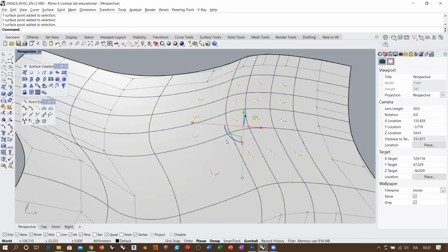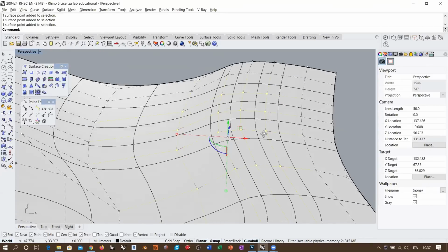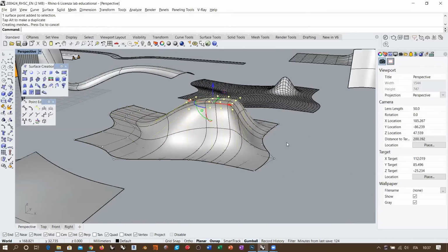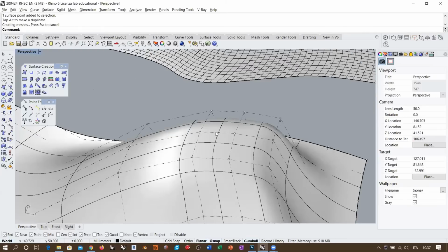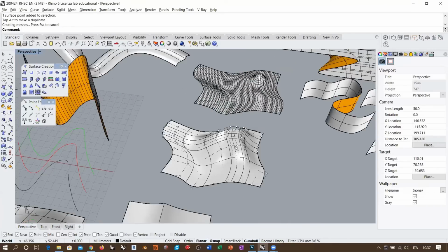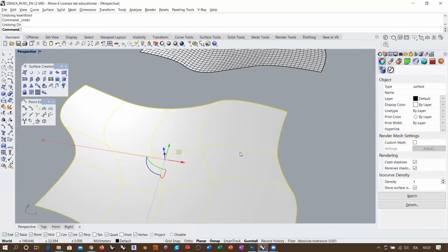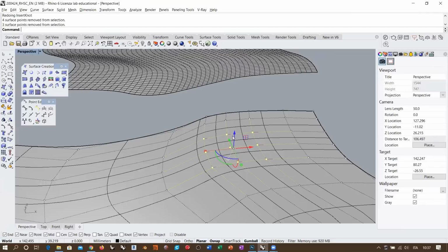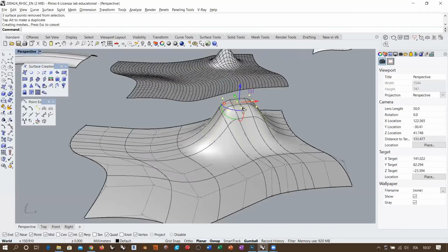So 4 by 4 control points will produce a flat area in the knot span that corresponds to the inner part of this region. So if I move everything up here, there will be a flat area more or less in this part here. Okay, so you see that we are creating this kind of nice bulge that we can control. We can control in several ways, because if I go back to this and deselect this point and this point, and I take this 3 by 3 set of points, I know that I can reach this height.